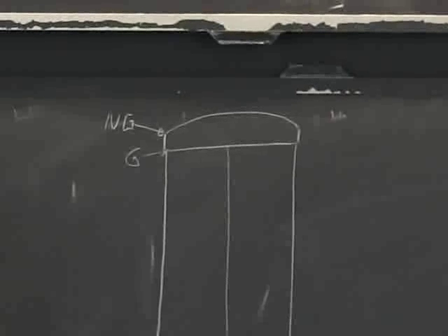But if there's a weld on it, just in the heat affected zone and in that area, there's so much residual stress that it's the equivalent of almost loading a full sample close to the yield strength. And that's where the cracks will start